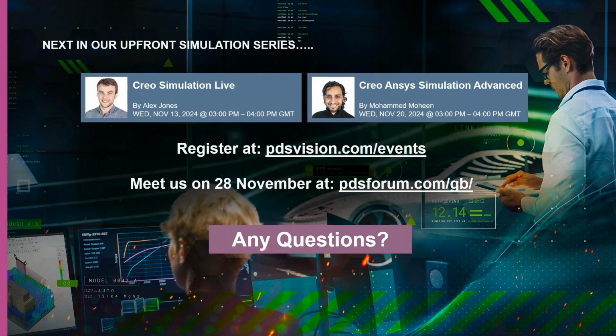But it's more for load transmission between parts rather than taking into account things like imperfections and residual stress. Welds for solid parts need to be defined in Creo Parametric using the weld wizard prior to entering Creo Simulate.